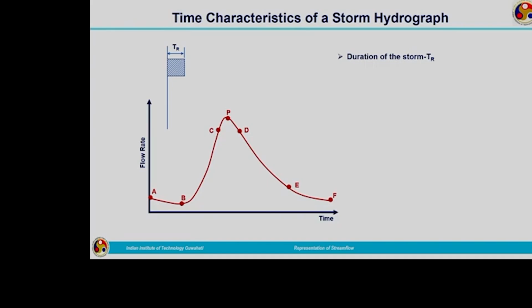This is a smooth curve. Actually, what is this hydrograph? A hydrograph is the curve representing the time distribution of runoff at the outlet of the catchment. The flow contributed by the catchment at the outlet is measured and plotted. Depending on the type of the catchment, the outflow at the outlet will be different. It may not always be a smooth curve as shown in this figure.